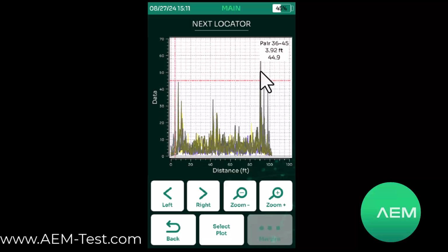And then right out here at the far end, we see one out at about 90 feet. And that is another crosstalk failure. And then there's one midspan in the cable at about 43 feet. So each of these events are a little different.